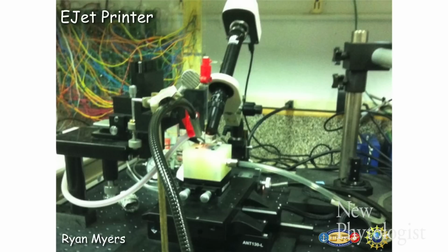It's really not fun. So we've gone to a new technology which is called electrohydrodynamic or E-jet printing. And the way this works is you take a glass microelectrode, which is something that I really know how to work with, and you sputter coat it with gold, and then you put it over a stage that moves in X and Y, and then you put a very high voltage between the microelectrode and the stage of between 5 and 800 volts.